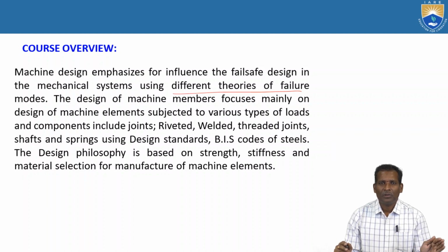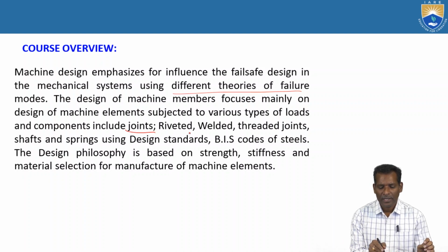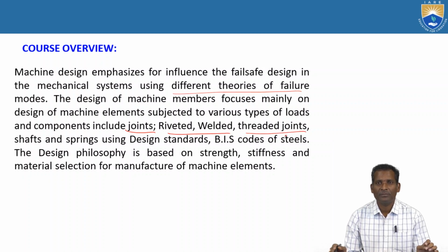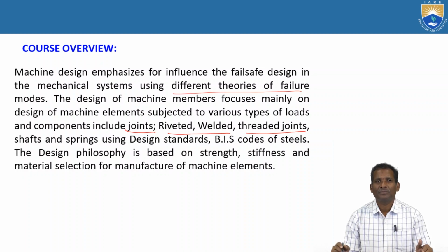The design of machinery members focuses mainly on the design of machine elements subject to various types of loads, and components including joints, rivets, and welded and threaded joints. There are permanent type joints and temporary type joints. Riveted joints and welded joints come under permanent type joints, and threaded joints are an example of temporary joints.